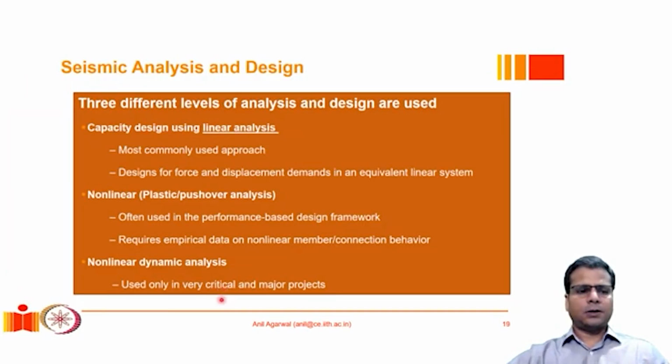There are three different levels of analysis and design methodologies that can be employed. The one that is most commonly used by structural designers for everyday structures, including high-rise structures too, is known as capacity design using linear analysis. This is also sometimes referred to as response spectrum based analysis or response spectrum based design.